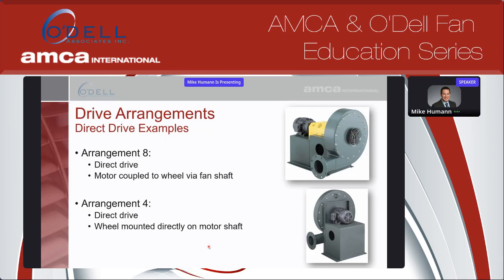We see a lot more direct drive fans now than we do belt drive fans. It's kind of the trend. And when you can, ideally, if you make an arrangement 4 work for your application, that's certainly something you're going to want to explore, because it is cost efficient and still gives you a nice bang for your buck. It has a small footprint, so there's certainly something to be said for that. You see a lot of people trying to use as many arrangement 4 fans as possible.